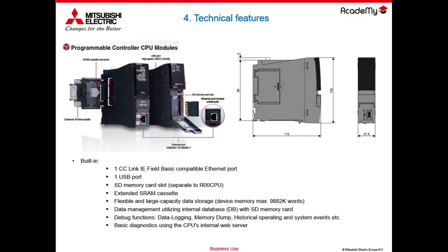One is the USB 2.0 port, usually using the Ethernet alternative to connect to GX Works3, and another port up here, darker in color, under which we find the LEDs. Some LEDs refer, for example, to the battery status and the execution state of the PLC, so whether in run, stop or error, and a slot to contain an SD memory card.